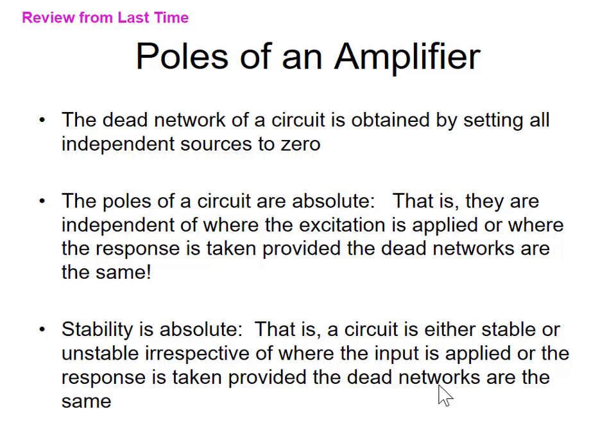And if I apply Kirchhoff's current law to every node, I'll get an equation, and this is equal to some excitation matrix. This is the form that we have for the nodal equations for a circuit. This is a vector of all the node voltages in the circuit. So I want to solve this circuit, I need all the node voltages.